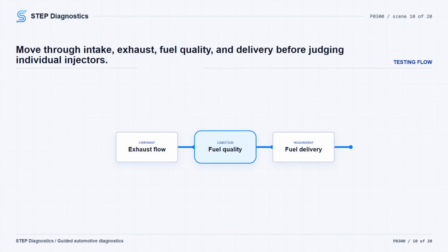If the oiling checks pass, inspect the intake side. Look over the intake plumbing for restriction, check the air filter for excessive debris, and check the engine for vacuum leaks. If you find a leak or restriction, repair it and verify the repair. If the intake is clean, check the exhaust for physical damage that could cause restriction and excessive backflow. Let the engine idle and check flow at the tailpipe. Repair any exhaust restriction before continuing.